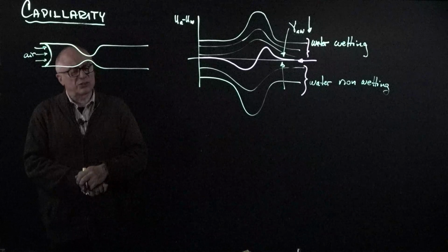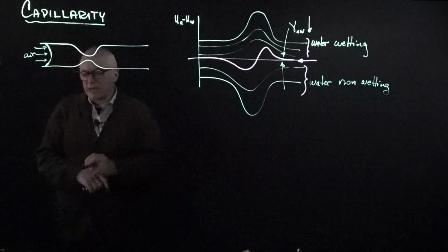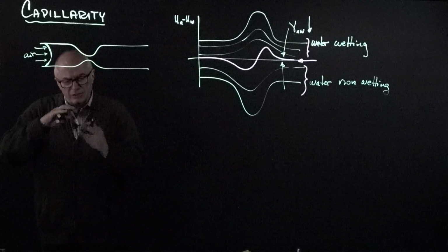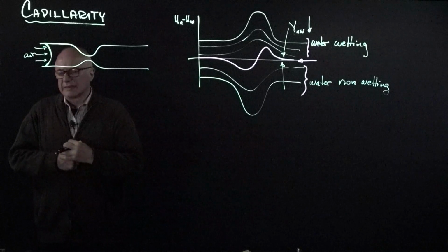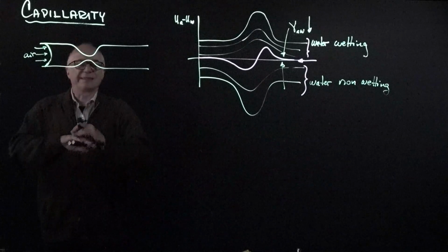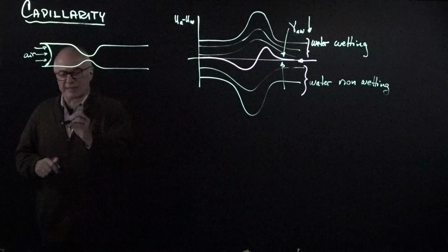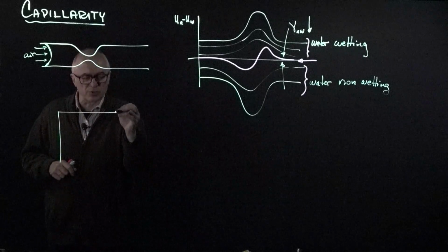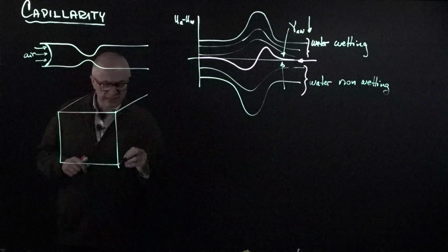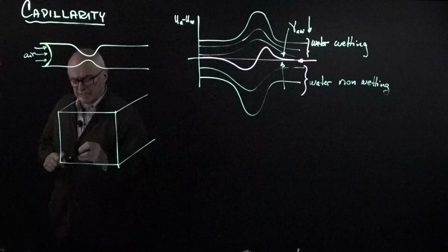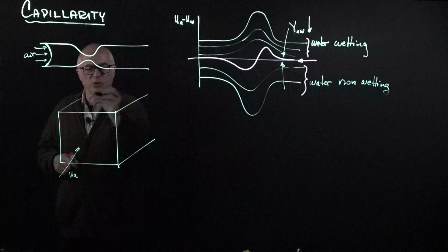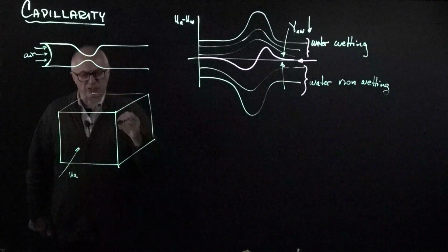Now this is the longitudinal pore geometry. If we actually look at the pore geometry, it's full of crevices and little corners along the surface roughness of the particles. So what is the effect of the transverse geometry of the pore? Let's take a very weird example, but let's say that we're working with a capillary tube that is a square. At the beginning, it's filled with water, and now I begin pressurizing u_air while I hold u_water constant. This is a very long capillary tube.